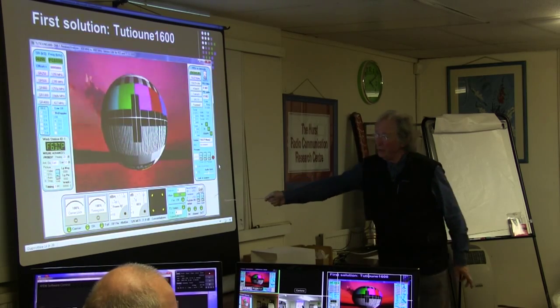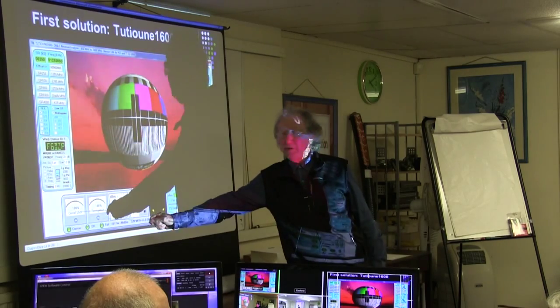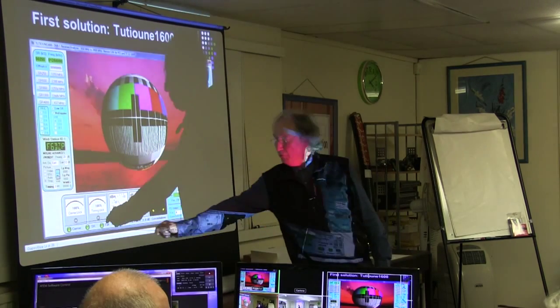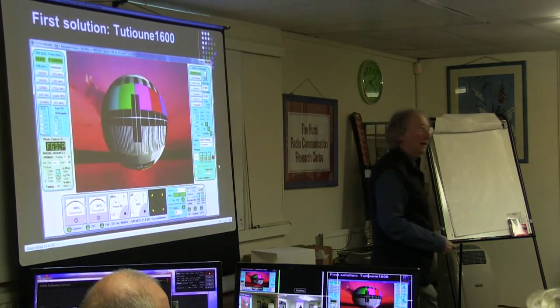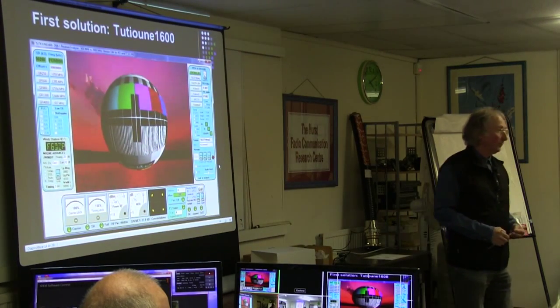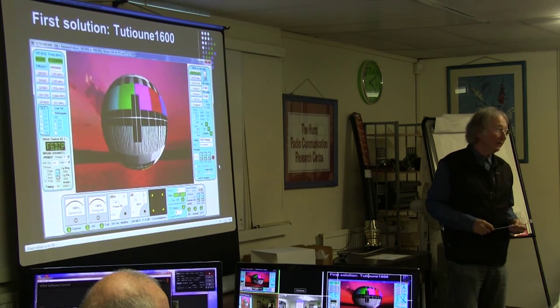And you have here all the measurements. What will be very important when you want to receive, you look at these two LEDs, the carrier lock and symbol rate lock. And when you have difficulties, it will be with the carrier lock.